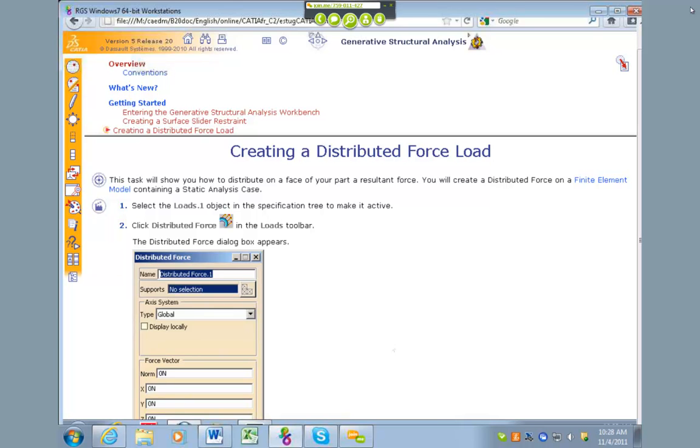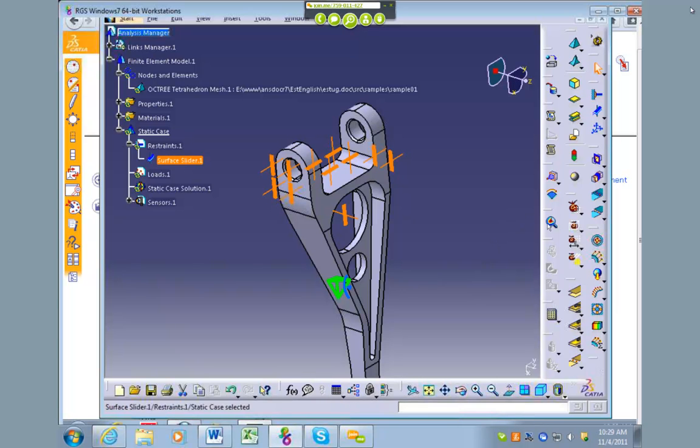So if your race car, for example, we're looking at the bumper part maybe, there would be two constraints in there showing where the screws are holding the bumper in place, and then you'd need a load showing where the impact would occur. And then you can apply an actual value to that load to simulate how hard you're hitting something. So to apply a load, there's a distributed force button. The distributed force button is kind of a little curve here with some arrows on it. So if you come into Catia, there should be this one right here, distributed force.